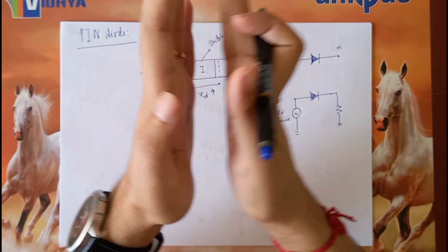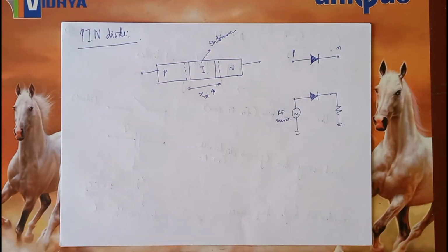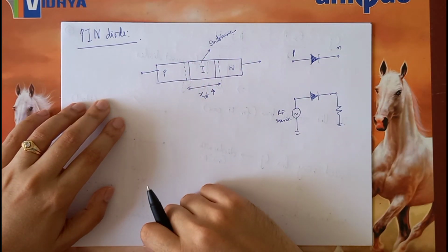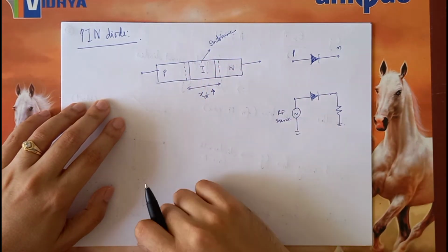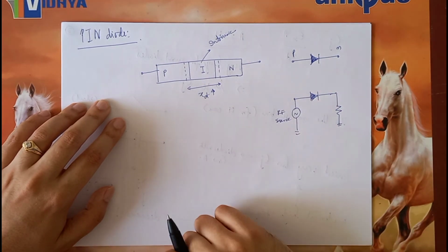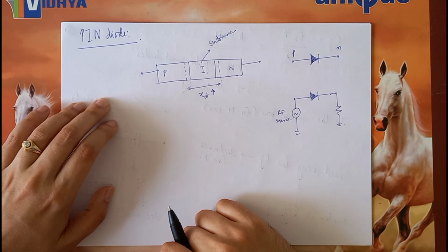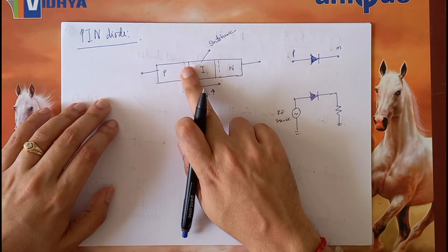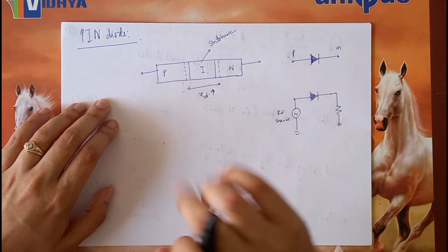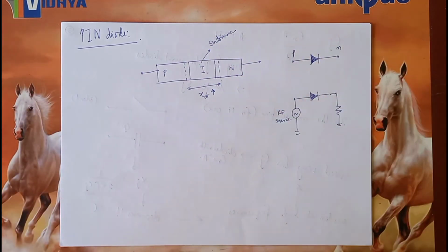We are increasing the depletion width to get a smaller junction capacitance, but we are inviting another kind of trouble. That is, the depletion region by itself has its own built-in potential, and the electric field associated with it does not allow the free charges from the P side to the N side, or the N side to the P side, to travel that fast. Think of it this way.